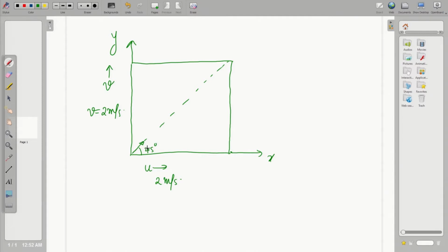So, if you have a square domain like the one we have sketched over here, the phi variation would depend on the boundary conditions that you are specifying. Let us say phi is specified as 0 on the east and the south faces, and on the north face and the west face we are specifying phi equal to 100.